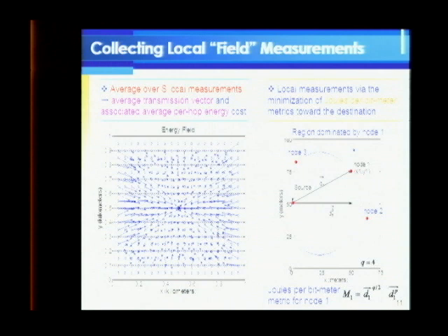We can actually draw a region which is similar in a sense to the enclosure work. If I find the neighbor node 1 here, I can compare, in terms of the path loss metric, the energy consumption to get here per meter versus the joules per bit meter cost for all the other locations. And we find that if the nodes fall in this shaded region here, then they always have joules per bit meter costs that are higher than this location here. So once you find this neighbor, the only region that you need to search for more neighbors is this region, which is easy to do. You do not need to look beyond this boundary in order to find the minimum joules per bit meter metric. So locally, you can use this technique to find nodes and minimize the joules per bit meter metric. And every node does this in the cells when they visit different cells.